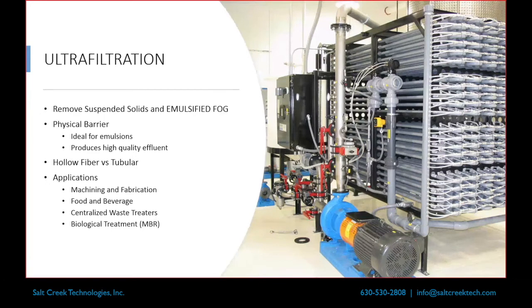So, ultrafiltration. This is maybe not as popular of a conversation here, but it is a technology or membranes as far as their performance. They are very good at dealing with emulsified oils. They are also very good at removing suspended solids.